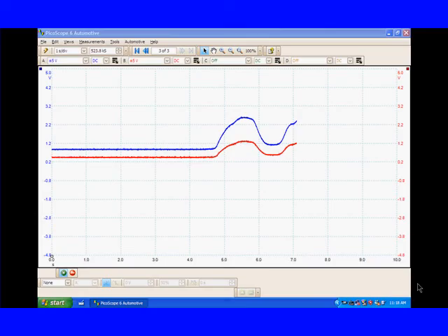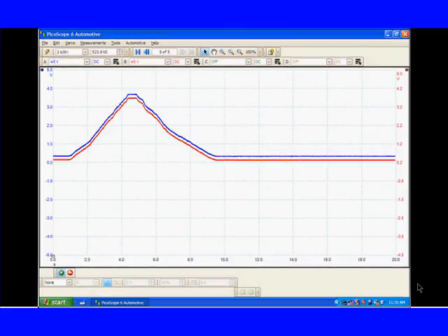We're going to be using our lab scope. Now what we've done here, slightly different, and we keep telling you we're going to change things. We have changed this to 1 second per division because we're working a little faster and we're doing it as a two-man job. And we're just looking at changes. And we're going to be watching for any changes where these two don't agree. So here's another sweep test. We're back to our 2 seconds as a one-man job.